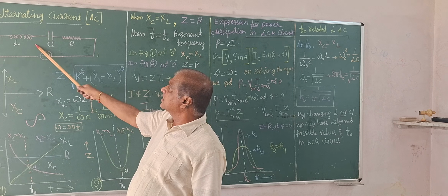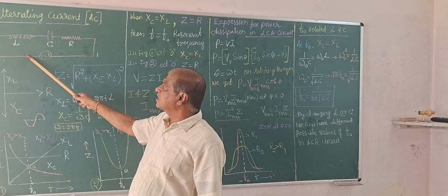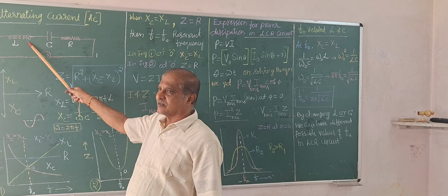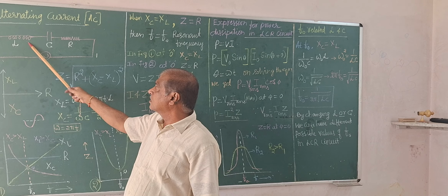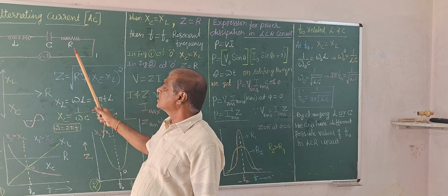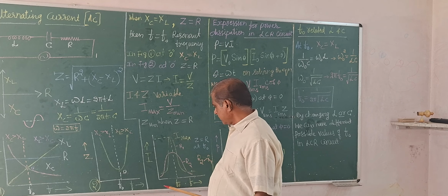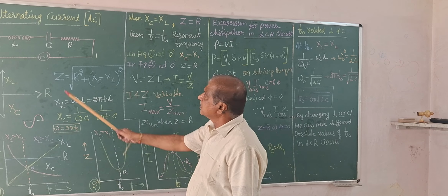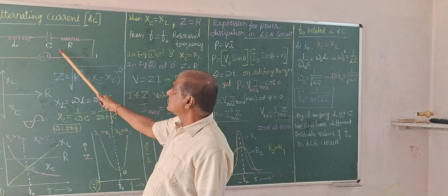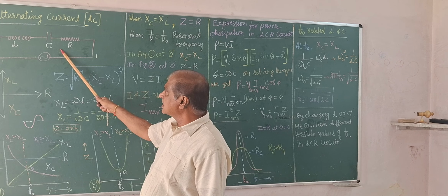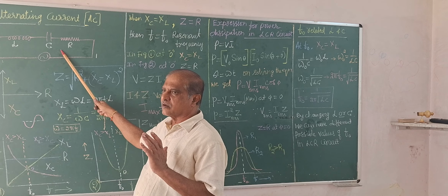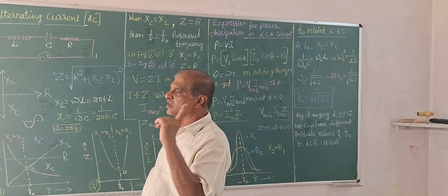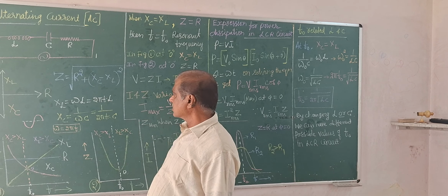So any other frequencies, AC signals of any other frequency are getting restricted, are getting filtered out, not passing through this LCR. Those are the frequencies away from this. That is the reason the AC LCR circuit acts as a very good filter for all other frequencies and allows only one frequency, the filtering concept.